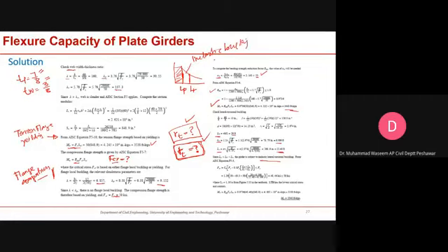The bending moment M will be greater than My, but it is less than MP. So this section is not going to reach MP. It is going to fail by inelastic buckling if the value is between LB and LR. So for this case, you need FCR. FCR you can calculate, and for this, you have to calculate the CB value.